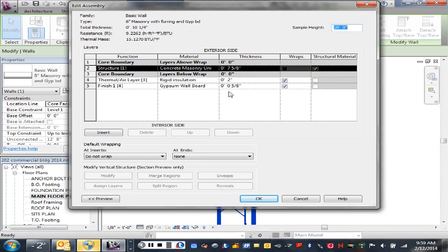Okay, when we get to the top of this exterior wall, like I just talked about in the levels, we're going to switch to a thinner wall, right? So a couple ways of doing that. We can put in a reveal, so that 8-inch now becomes a 4-inch or whatever it has to be. Or we can bring our 8-inch masonry wall up to a height of whatever it has to be, 10 foot or whatever, and then on top of that put a different wall.